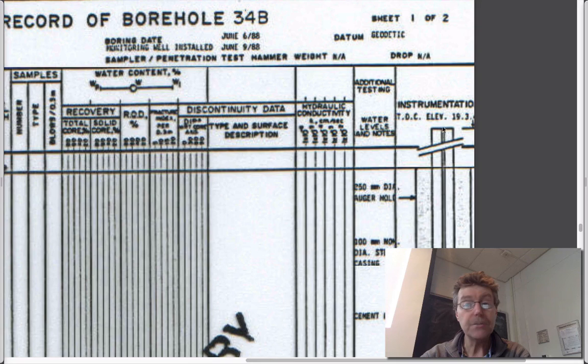So in this case it has a hole that's cased, has a second casing inside that just sockets in here. It has a tube that goes all the way into this zone where you want to measure pressures and can run slug tests to measure permeability at any time. And you seal this in by capping this, and then you can drop an instrument down here to measure the depth to the water table.